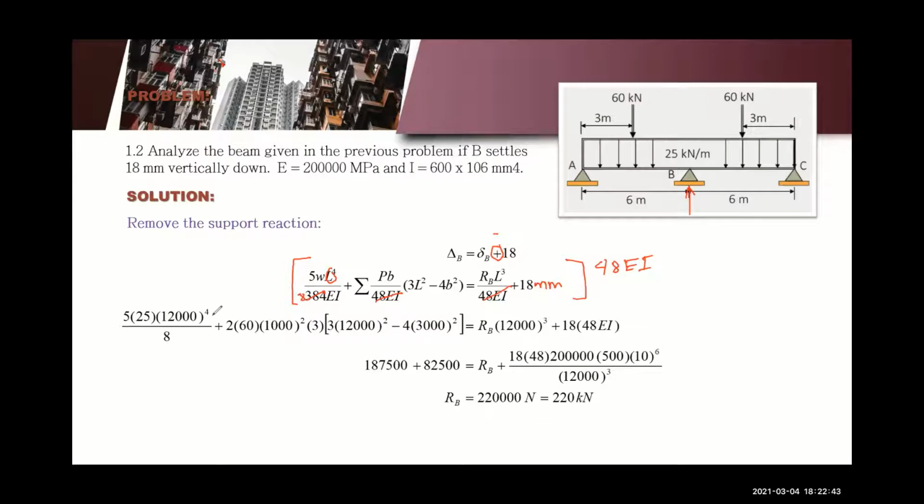So, simplify first for a shorter solution. And then, every load here is convert natin into Newton. Ang lahat naman ng distance will be converted into millimeters. So we have 25 kilonewton per meter is the same with 25 Newton per millimeter. So you don't need to add a multiplier. Diba? Kapag i-convert mo siya, just 1,000 divided by 1,000. So similar. So this is 25 Newton per millimeter.